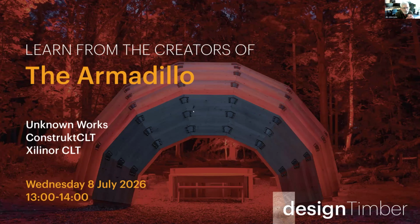So at Trinity Buoy Wharf, we used resin anchors, and we bolted down through the alu start so that when it was demounted, we could take the alu start straight off because it was only bolted on, and reuse it at Houghton. And then we could just cut the bolts and leave as small a footprint as possible at the wharf. The idea was to have a very light touch.